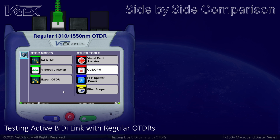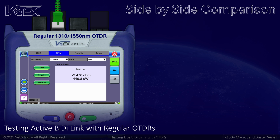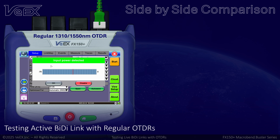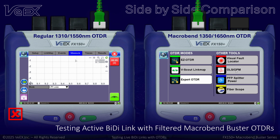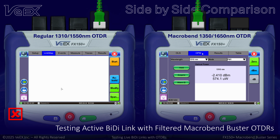So, here is what happens if you try to use a regular 1310 and 1550 OTDR to test a bidirectional link with live signals. First, use the OPM function to check for signal present in the link. If the link is active, technically you should stop here. However, let's show what happens if you still try to obtain an OTDR trace. The regular OTDR should give you a warning. If you ignore the warning and press start, its sensor may not see the reflections and no results would be displayed. Now, let's try the filtered Macrobend Buster OTDR with 1350 and 1650 nanometer pulses.